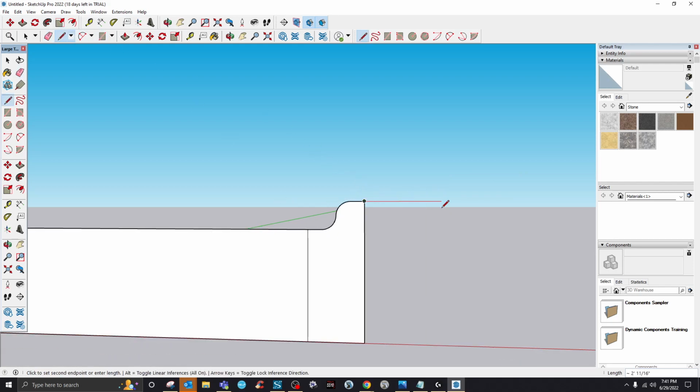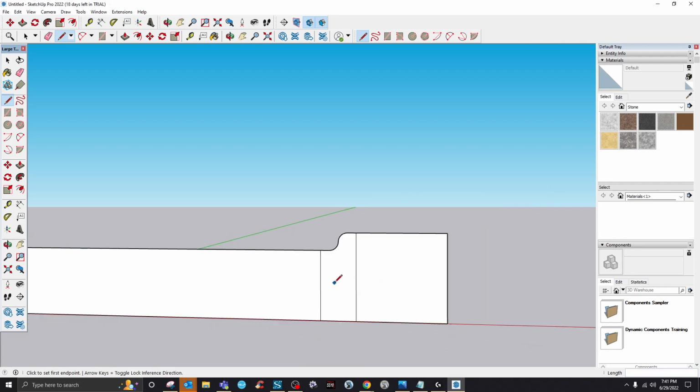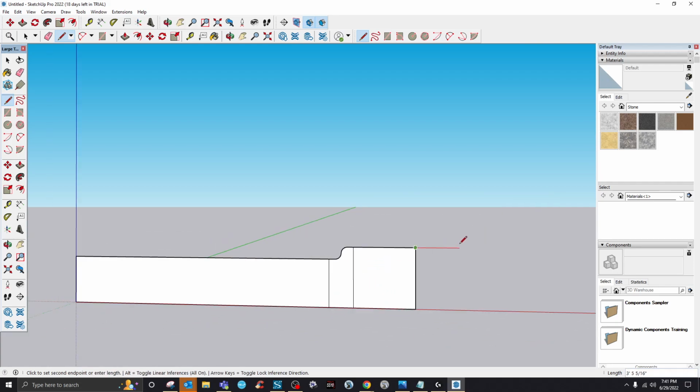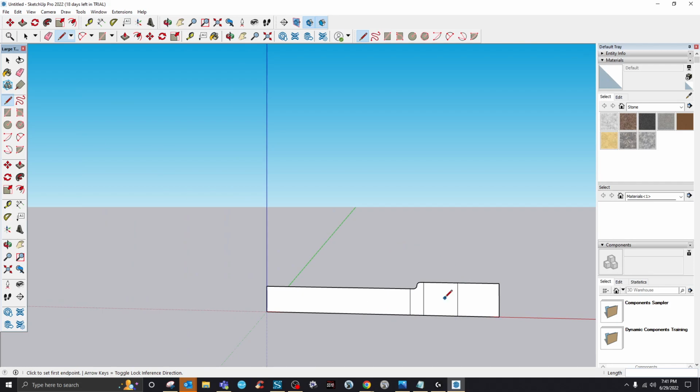Let's add a sidewalk. Let's make it 5. Lovely sidewalk. And then let's add some green area. Make it 7, I guess, or 6. Again, when you're doing this, you're gonna have a typical section with you and you're just gonna try to mimic it. So I did this side.